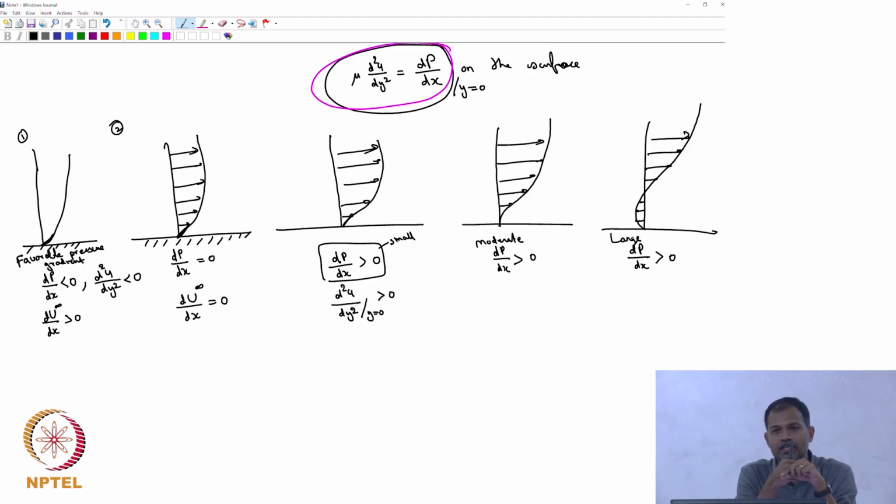That's what we call flow separation. So whenever we talked about those diverging sections and so on, I always drew fluid flowing in the opposite direction, right? This is because of this particular reason. This is called boundary layer separation. The external pressure gradient will cause fluid on the wall to flow in the opposite direction.